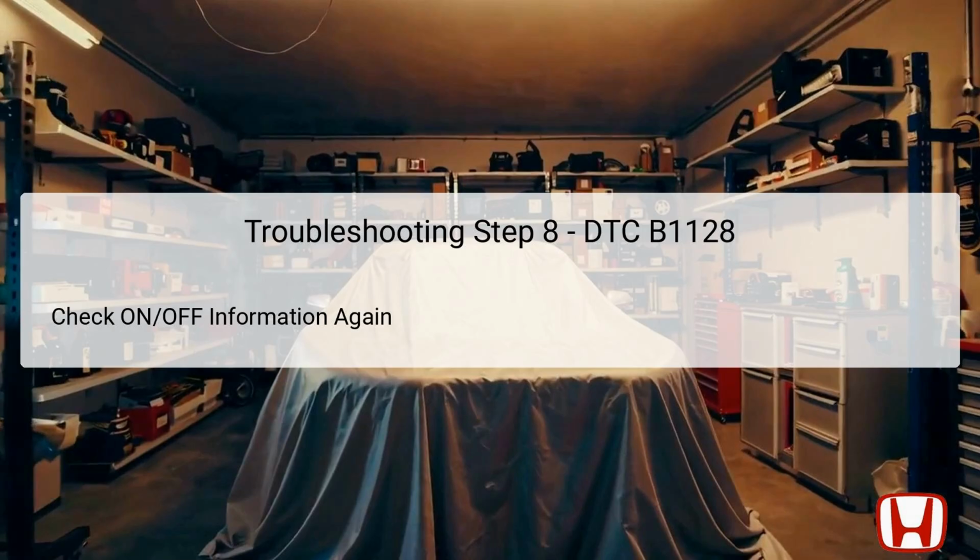After disconnecting the power window master switch, you again need to check the on-off information of the driver's door lock switch lock and driver's door lock switch unlock. This step provides a second opportunity to assess whether the signals sent by the door lock switch are still conflicting.